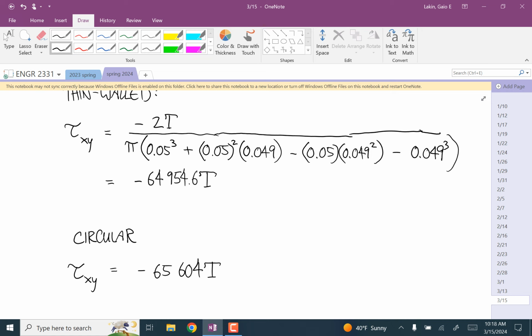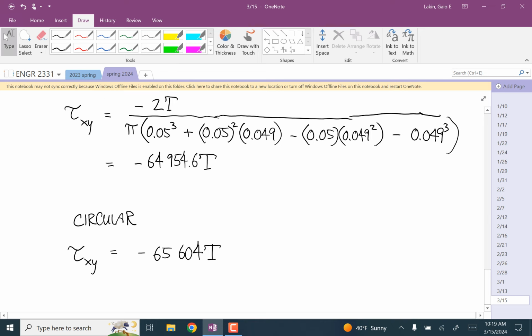That's a millimeter thickness, which, by the way, steel tubes are surprisingly thin for whatever application you're using. If you can picture an old bike that you find in a garage sale, the thickness of those tubes is right around a millimeter, and it feels like a pretty substantial thing. It's not like it flexes if you try to flex it. So a tube with a millimeter thickness can support a lot of load. But so there you go for that.